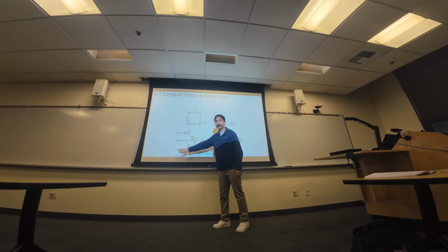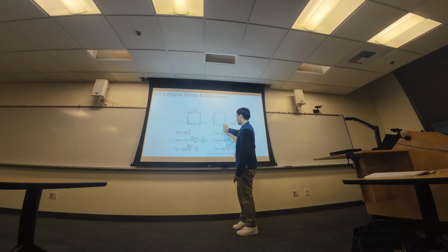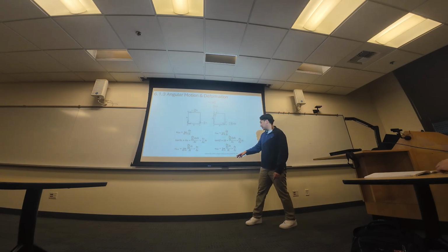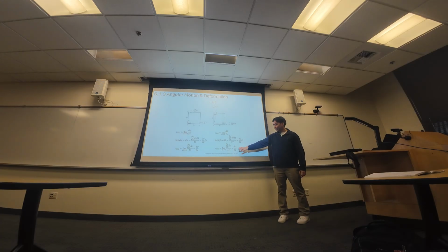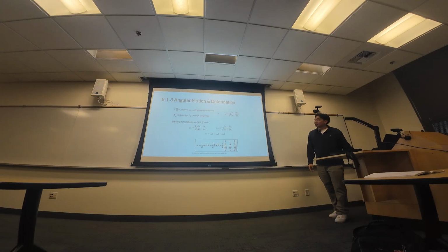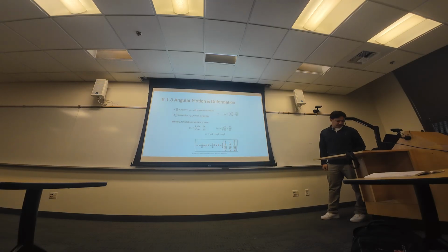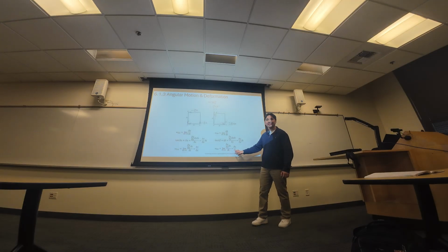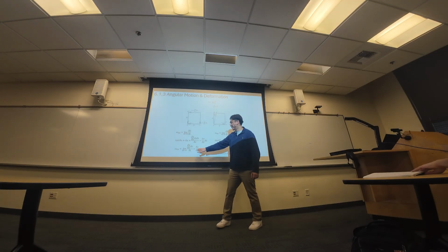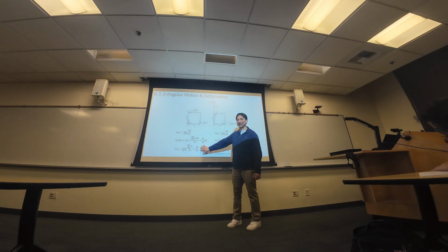This means angular velocity from O to A, right? Angular velocity from O to B is equal to the partial derivative of the velocity in the x direction with respect to x. Same thing here: partial derivative of velocity in the u direction with respect to y. I didn't box it here, but I'll edit this. This is what you want to box, this here. So omega O to A is equal to this.